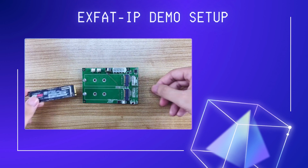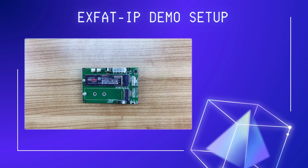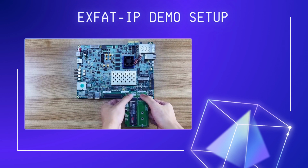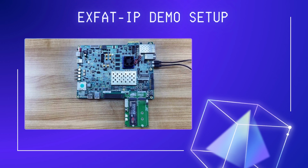Begin by connecting an NVMe SSD to the drive 1 M.2 slot on the AB17 adapter. Next, connect the AB17 adapter to the HPC connector on the FPGA board. Use two micro USB cables for JTAG programming and serial console connections. To power up the FPGA board, plug in the power adapter. With these connections in place, we're ready to proceed with the exFAT-IP demo.